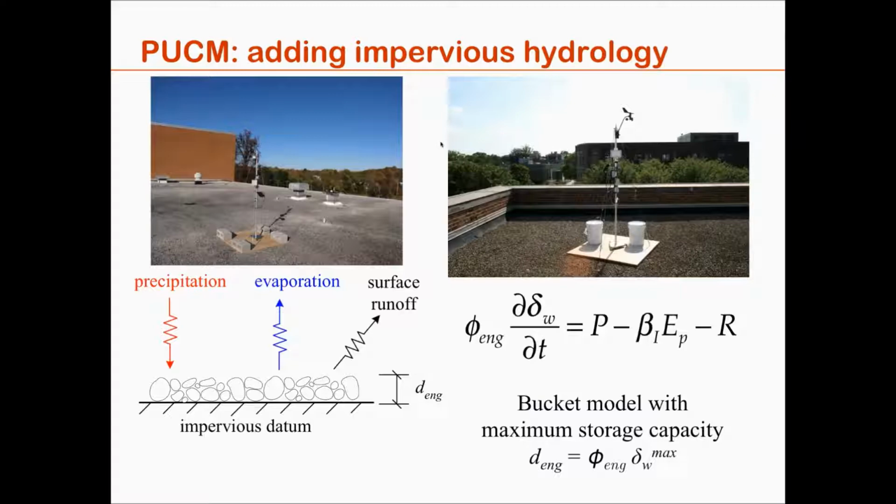We've also implemented something that's important, which is the fact that impervious surfaces are not completely dry. A lot of the roofs at UMBC campus or on Princeton campus are composed of gravel, and these roofs can become a reservoir that stores a significant layer of water if it rains. Similarly, all other urban materials have some storage capacity. So we now model these impervious storage capacities as a reservoir that is filled by precipitation.